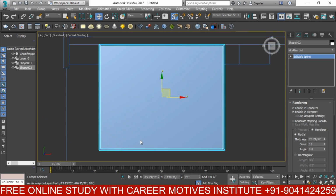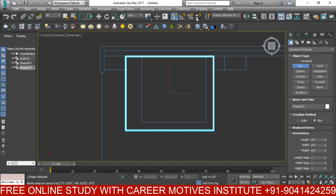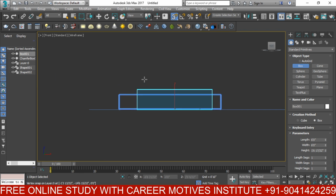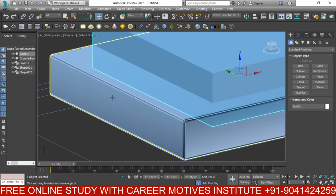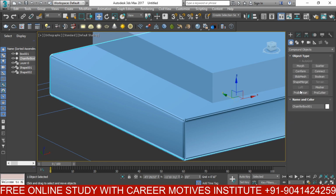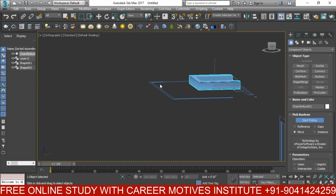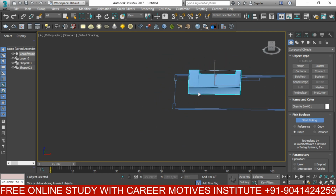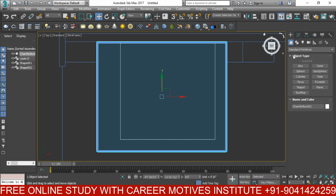Now I'm going to detach the inner part. I'm going to pro boolean the inner part. I have selected this and I'm moving it upward. I'm selecting the chamfer box, compound object, pro boolean, start picking, and the inner part is detached. Now I'm going to create the mattress.